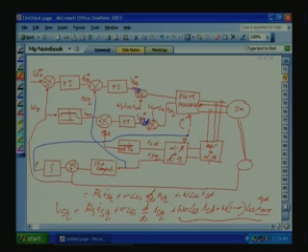So what is the advantage? This PI controller has to vary VSQ only for variation in the ISQ. So the variation for the PI is limited only to the ISQ here, and the ISD variation we feed forward here, so it need not come through the PI control. So it will also increase the response of the system. This way, for voltage control inverters with voltage as the variable for the PWM, we can use this type of closed loop scheme for the vector control application.